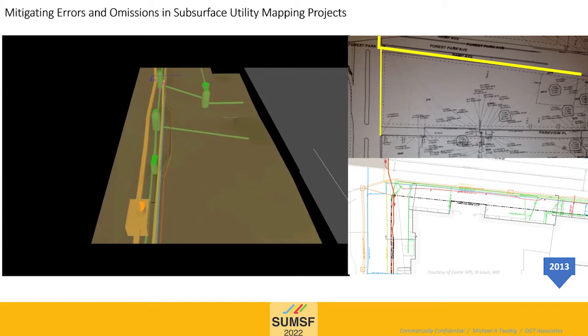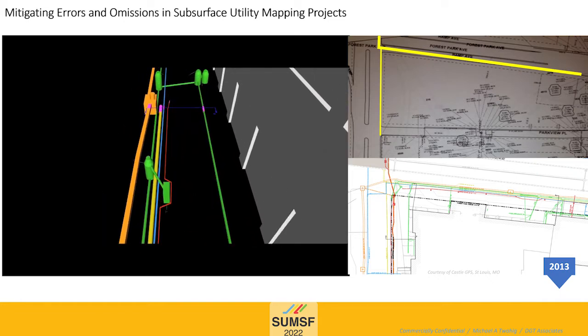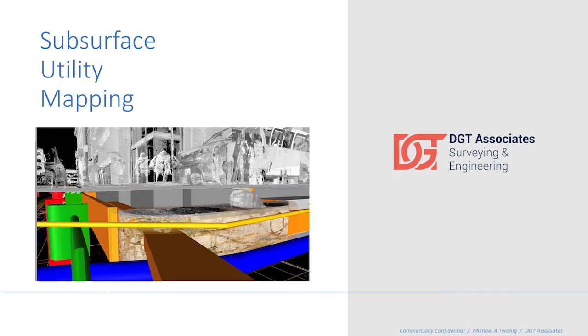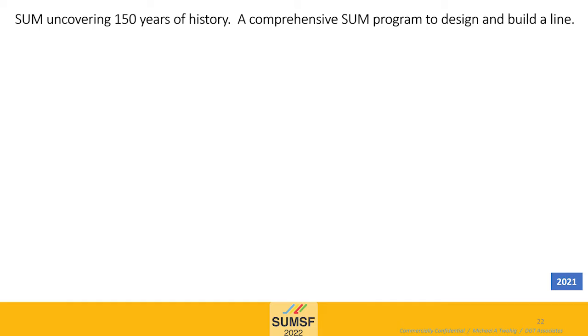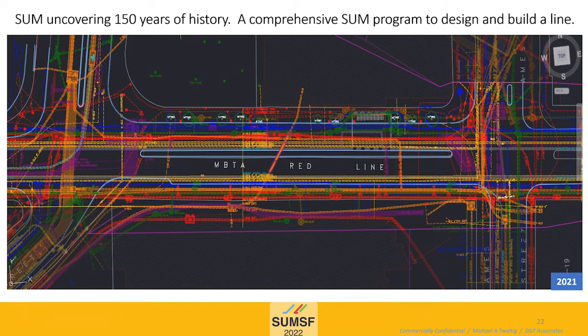So how do you find this type of critical infrastructure before construction? And you definitely need to find it in the early stages of design to mitigate any of the impacts and the safety concerns on major works. So subsurface utility mapping is something we focus on, and applying the survey tools that we have in current day practices has made it very, very easy to do this. So we're doing LiDAR scanning and sighting chambers, and that helps us move out of a 2D environment into a 3D environment. And over the years, how do we turn back to history and understand really what happens in these streets? And for us, this is a typical deliverable.